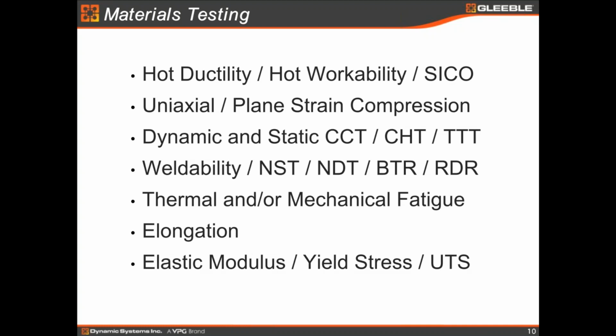Testing, I want to say it again, this testing is not MTS or instrument type of testing, because we don't have a standard. There is no standard in the world for hot ductility, for hot workability, even a cycle procedure. There's no standard. It's just a testing technique that you can use for your research, for your problem solving. Uniaxial is very, very popular testing, but honestly, there is no standard in the world. Plane-strain compression, theoretically, there is no plane-strain compression at all, because obviously there's a limitation on the specimen size. But we call it plane-strain compression.